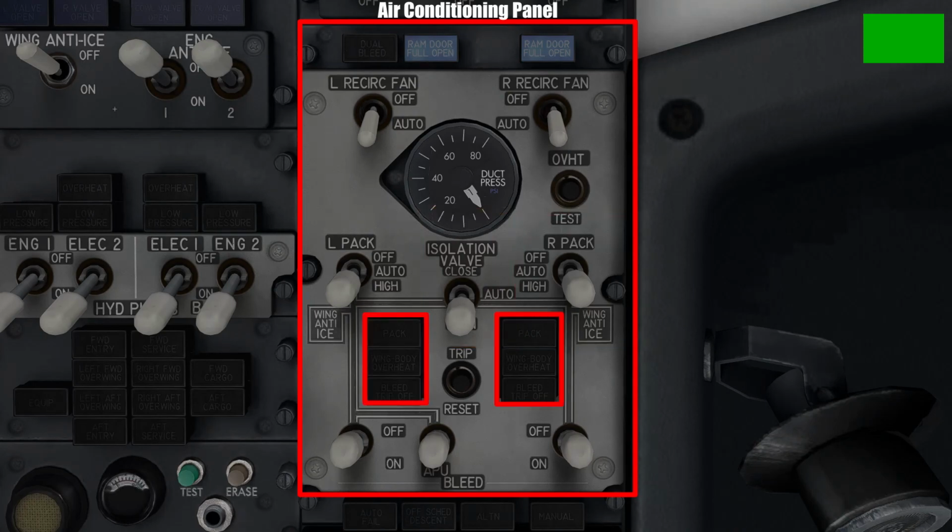Coming underneath, we have a pair of 3 warning lights that illuminate when a problem occurs with their associated systems. The first light on either side illuminates when there is a problem with either of the pack systems. The second, wing body overheat light illuminates when there is a leak in the bleed air ducts passing through the wings and the fuselage of the aircraft. We just tested this using the switch up above.